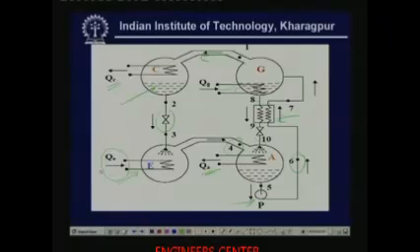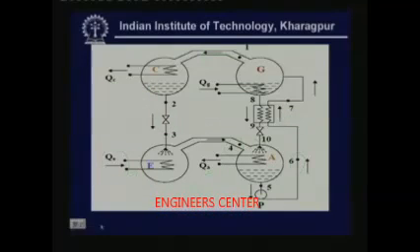So, you get the useful refrigeration effect QE, and the cycle continues. The vapor goes to the absorber, and the solution, which is now stronger in absorbent and weaker in refrigerant at point 8, flows through the solution heat exchanger, then the expansion device, and is then sprayed into the absorber so that it can again absorb the refrigerant vapor.